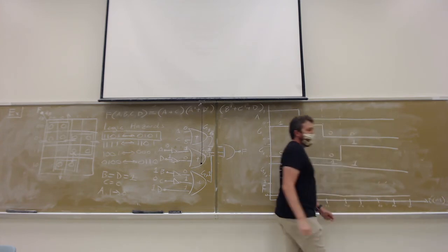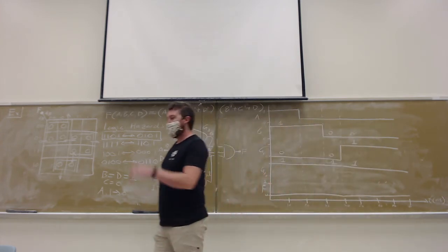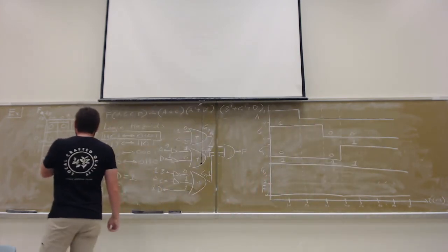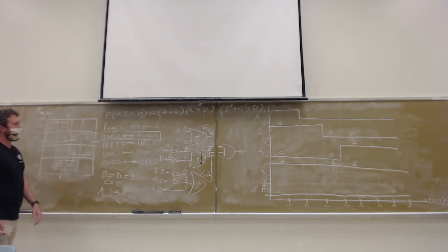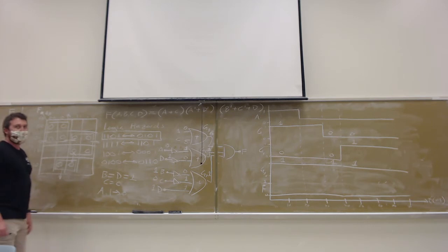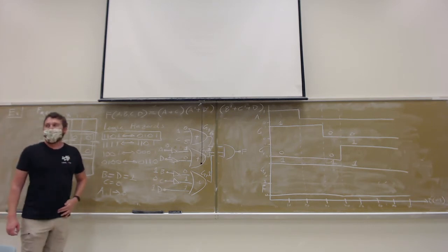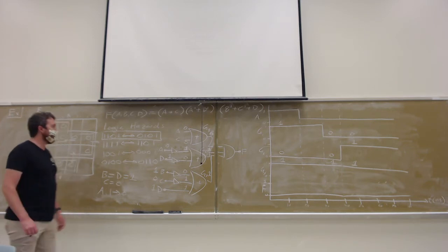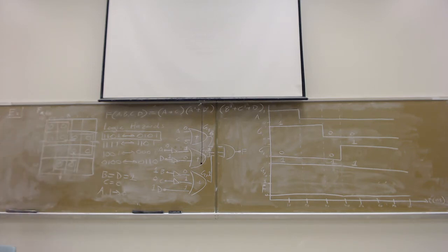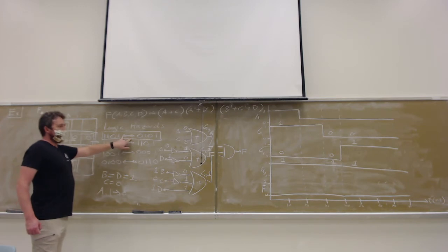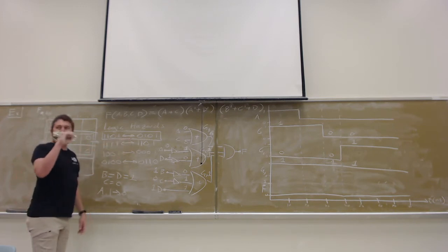So what happened? Nothing happened, right? But something was supposed to happen. We identified that a logic hazard was supposed to appear here, weren't we? Yeah. The logic hazard didn't happen. What's the deal? Well, the deal is that the order matters, right? The logic hazard exists at the transition, but it doesn't always exist in both directions, right?